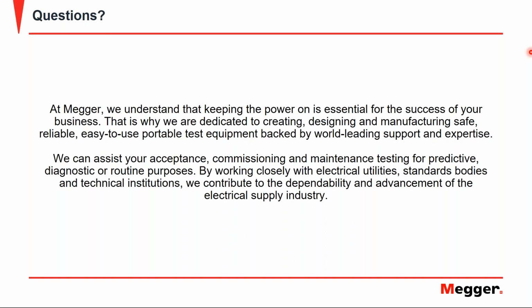Thanks, Charles. Hein, is such a claim of 5 picocoulombs in the field in compliance with what you explained about IEC 60270? The IEC 60270 is a standard which shows how to perform PD measurements, and over there no trending or picocoulomb values are mentioned.